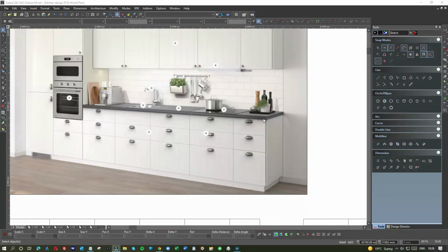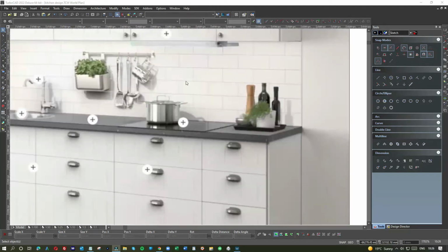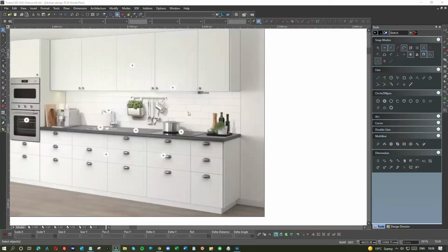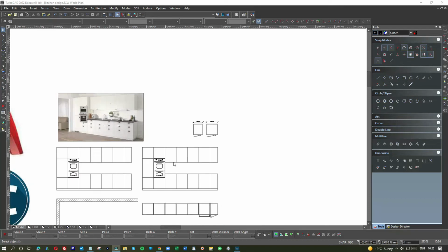The distance here, there is a limit as to how low you can come because of the standard heights above the hob, etc., from the point of view of fire safety. So you never want to come down too far above a hob. Common sense will prevail with regard to the sink. You don't want to be bringing these units down too far. You want to get easy access to the sink. So wall units, I can of course stagger, and it's not uncommon to see them staggered.